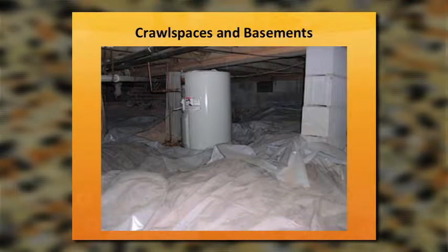For example, here we have a good vapor barrier that's been put down onto the floor. And you can tell that it's a rather lumpy floor. But nonetheless, that vapor barrier, that moisture barrier keeps groundwater from coming up and making that crawl space moist.